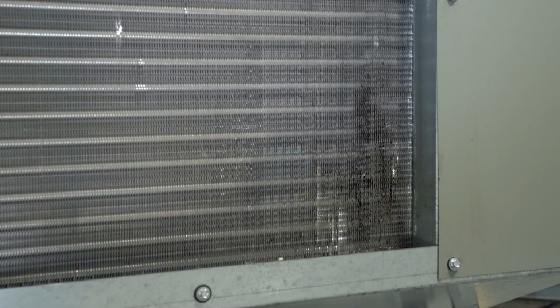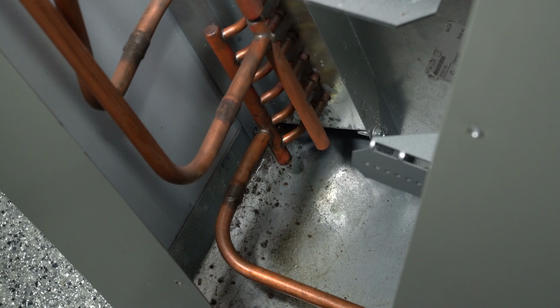Light oil residue from coil manufacturer may be visible on the outdoor coil after initial unit installation. This does not necessarily indicate a leak. Prior to investigating further, verify refrigerant pressures and performance. Typically, oil caused by a refrigerant leak will only be visible in a small section of the coil. If staining is near an accessible end of the coil, a repairable U-bend or header leak search should be performed.